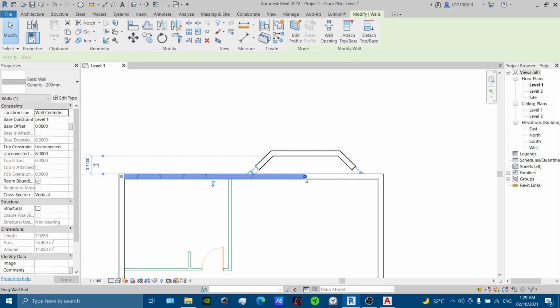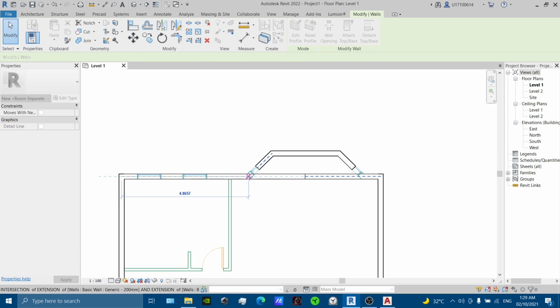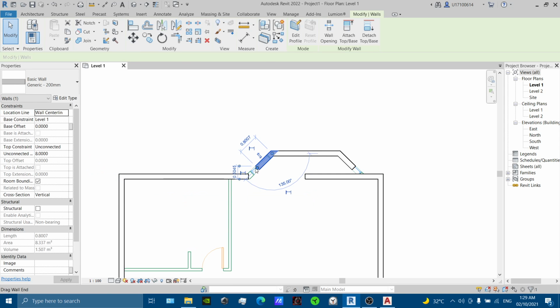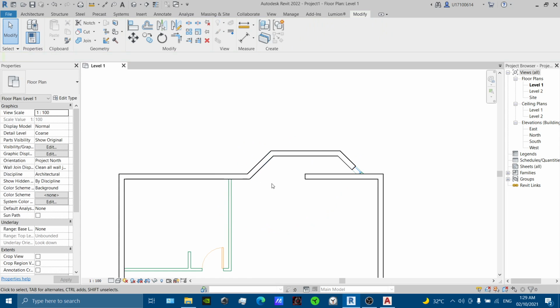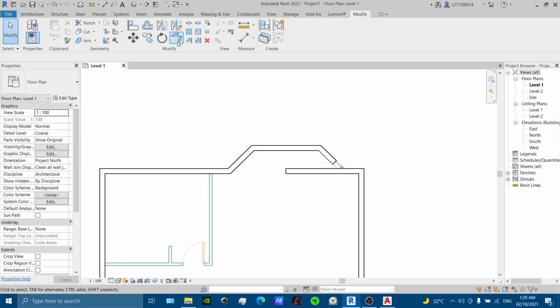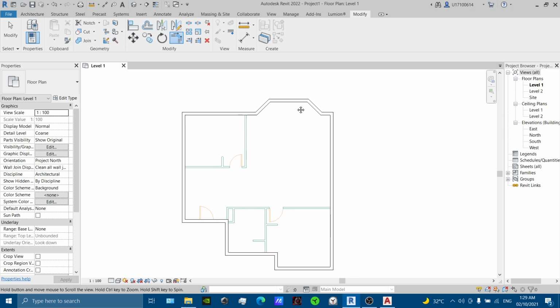One way to connect the walls now is we can drag the wall by clicking on the blue circle on its edge to the corner of the plan and connect the diagonal wall with it, as such. Another way to connect it is by using the Trim feature. It can be activated by pressing TR. This helps connect two walls without any need for dragging them back and forth.